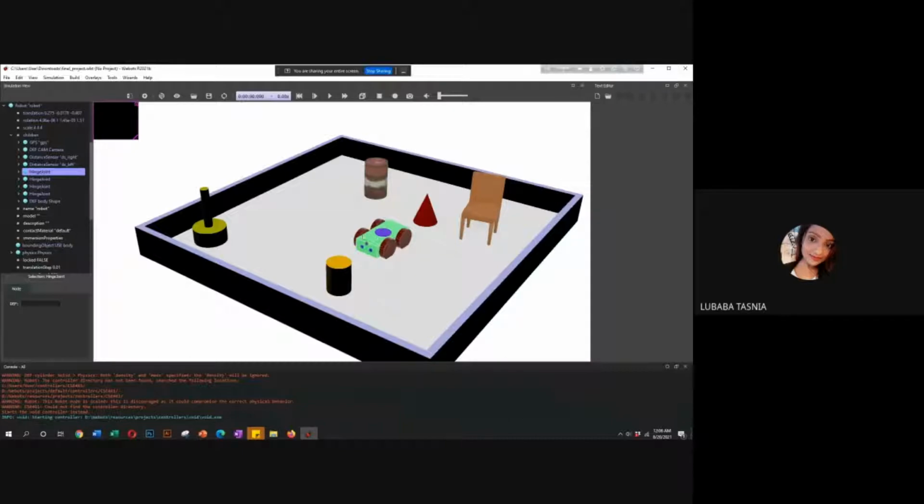And for my robot to move, here I use 4 rotational wheels. So these are my 4 hinge joints. One thing we must be careful about: inside the joint parameter of the hinge joint, we can see the anchor, and the anchor value must be the same as the translation value inside the endpoint solid. And here I set my rotational motor cylindrical shape. I did the same for all 4 of my hinge joints.